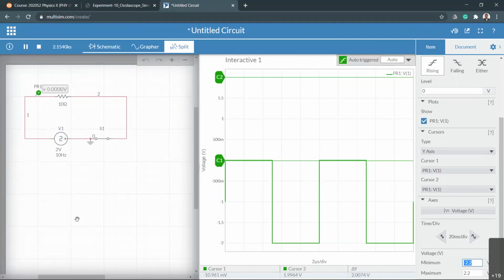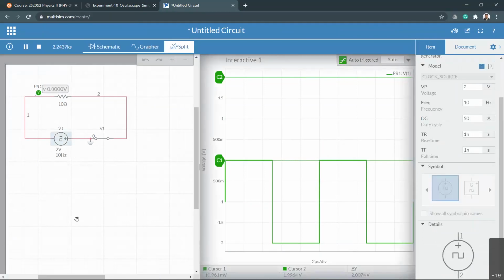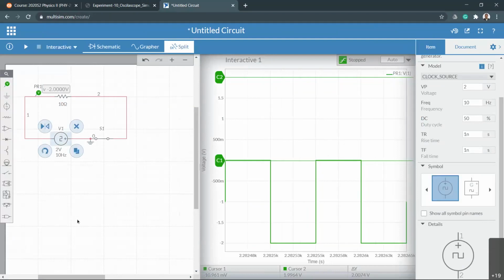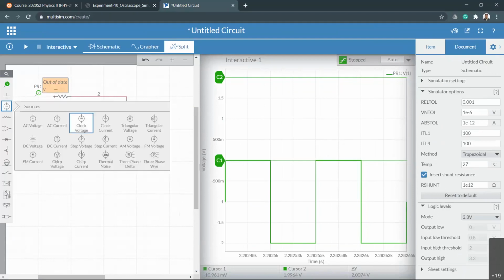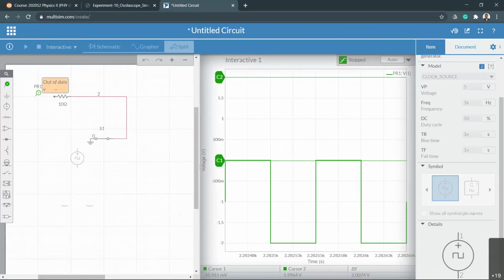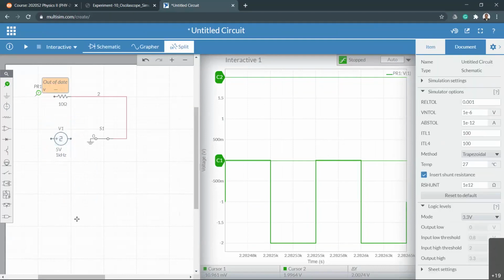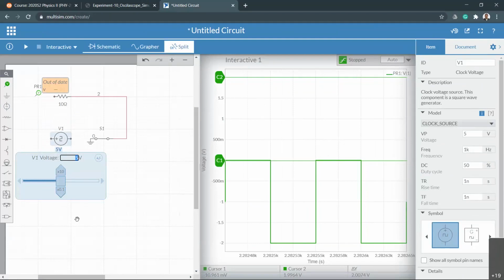So you can see when I connect the circuit right here, the source positive is connected into the ground. So that's not correct. So please change that. Otherwise you will not see the right shape. Okay, you need to rotate this. Let me do this. First we'll get rid of this one and then bring it back. Otherwise the circuit looks ugly. So you have to have a nice looking circuit here. So rotate this one until positive is on your left side. Okay. Then start connecting. Voltage, put it back into 1 volt. And frequency, put it back into 10 hertz.